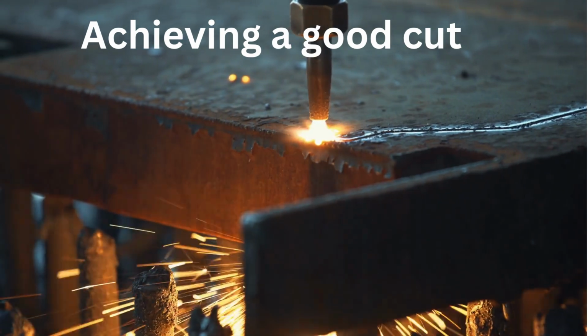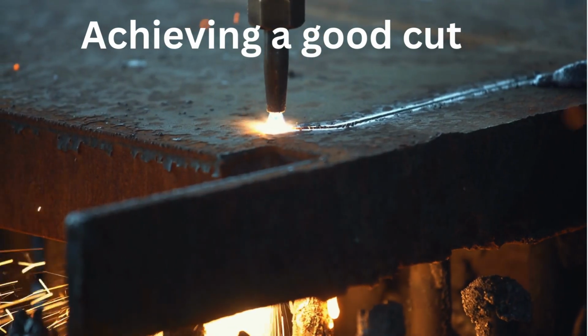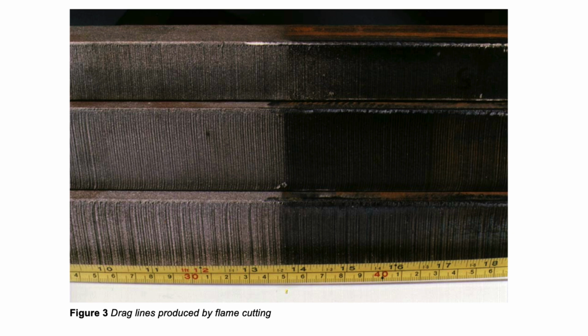Standards of cut surface quality are assessed in terms of squareness, perpendicularity, angularity, depth of dragline, and mean height of profile. However, these parameters are only appropriate to laboratory conditions, so the assessment of flame-cut surfaces on the shop floor is best achieved by having available samples which have been calibrated to the particular quality requirement so that they can be used as comparators. Figure 3 shows 3 flame-cut surfaces.